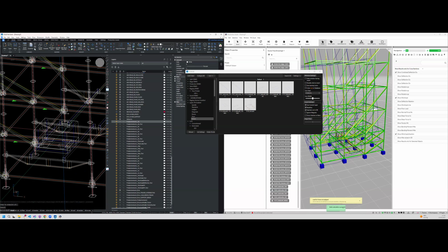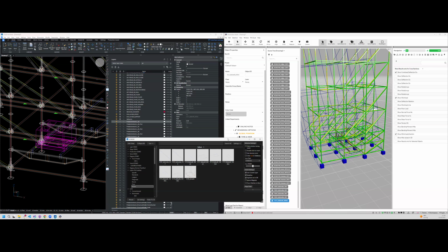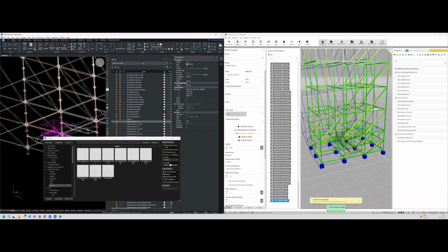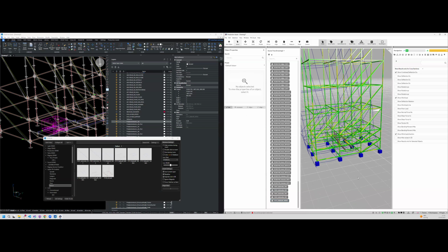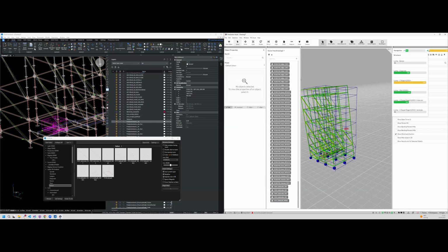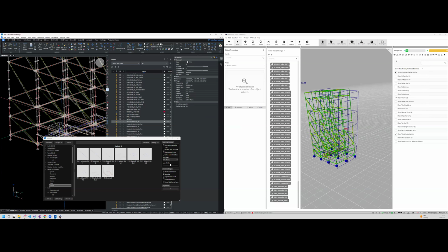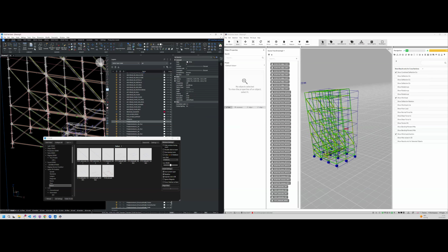And now this ballast that I have in here automatically is part of the calculation. I can take in the ballast, like 1,500 kilos, press enter, and then it will add these 1,500 kilograms of ballast to the structure. You see immediately this also increases the workload in here. So now you see that the problem is the O point on top of it, so that you've placed it in here. That is basically how you can calculate ballast and place it in here so you can make multiple bays. The idea is really to stay with the real thing that we need in order to calculate this.